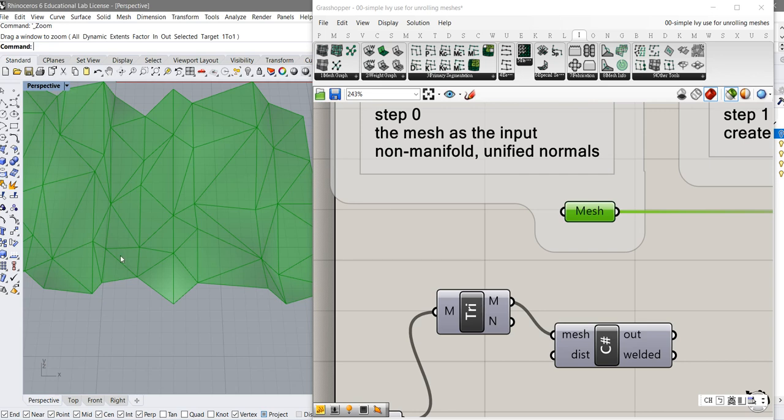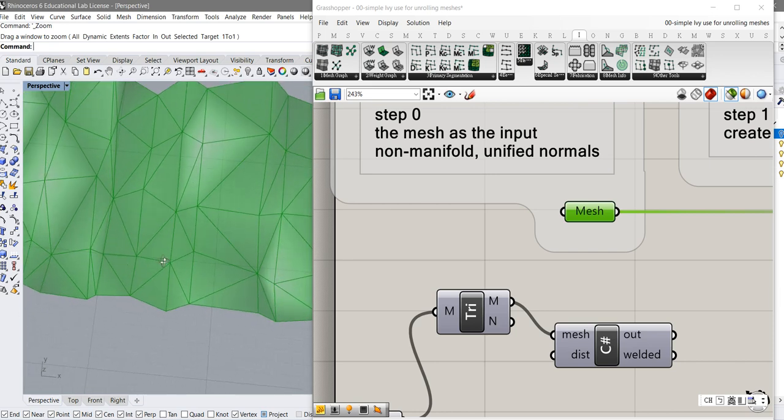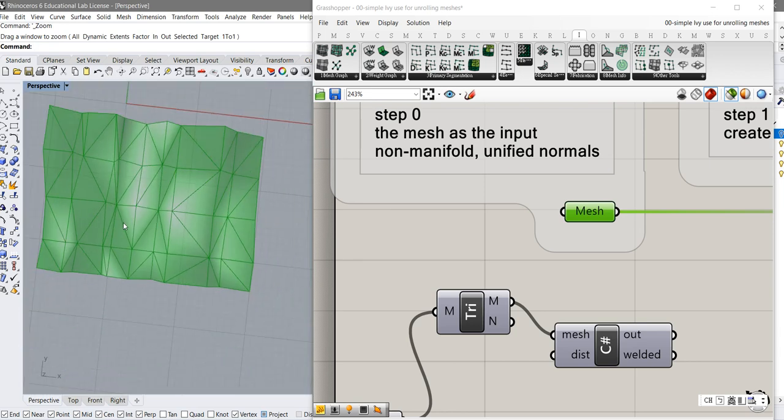But if we do that, there will be a lot of unnecessary cut, right? Because if we are able to fold, then we don't need to cut all the edges. Maybe we just need to cut a part of the edges. And then we can use like a CNC or laser cutting machine to cut the planar material. And then we fold on this line, either mountain fold or valley fold. And then we need to glue only the part that we are unable to unroll without overlapping.